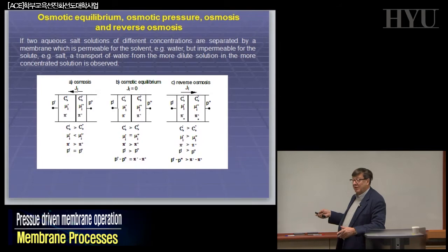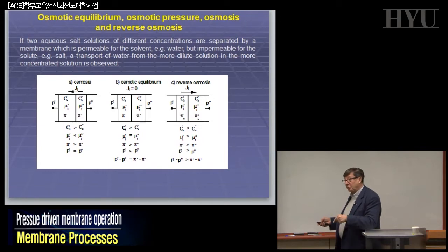For doing this, we have to apply a hydrostatic pressure on the seawater higher than the difference in the osmotic pressure, in such a way that the tendency of the fresh water to enter the sea will be destroyed by the tendency of the water to go out from the sea, having a hydrostatic pressure higher than the difference in osmotic pressure. That's why we call it reverse osmosis.